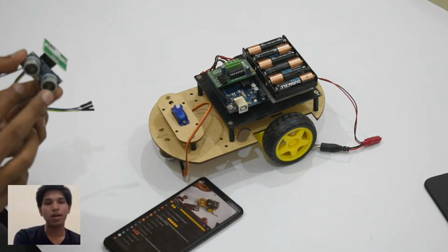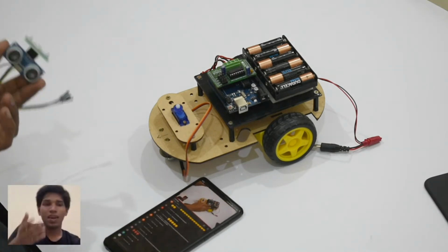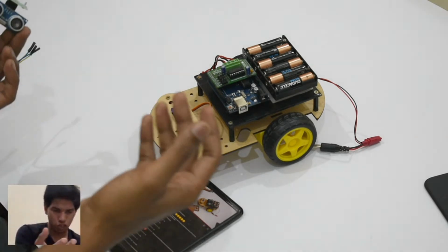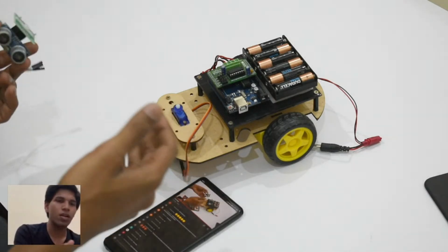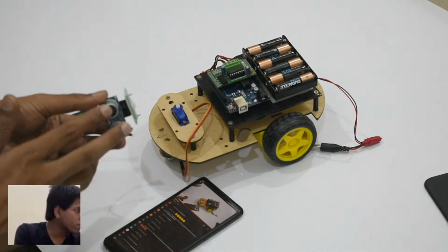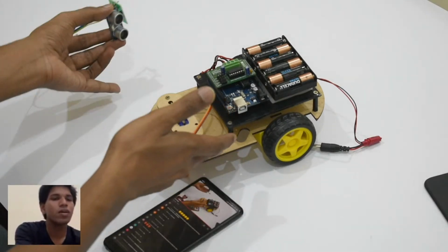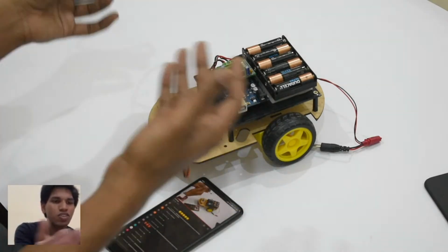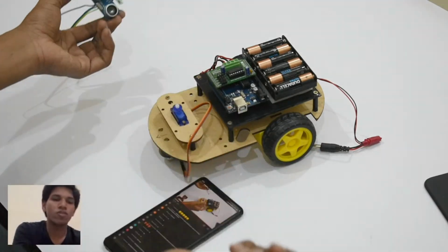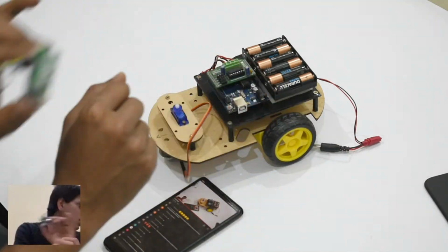You just have to tell it that if the distance calculated by this sensor is less than a specific limit, like, we don't want the car to reach an obstacle within a distance of 15 centimeters. So if the distance calculated by the ultrasonic sensor in front of the car is less than 15 centimeters, then stop moving, turn to the left and turn to the right and check the obstacle distance on its left and right side, and wherever it has more space, turn to that side and move in that direction. Simple as that. Just going to be really simple.